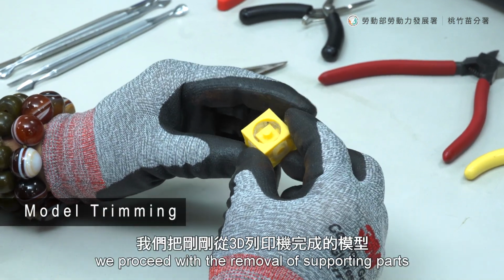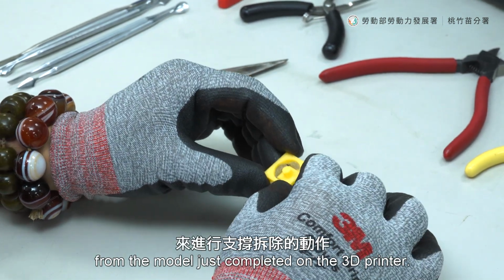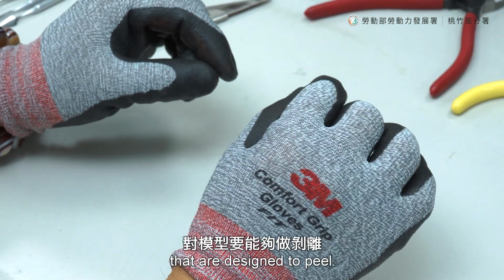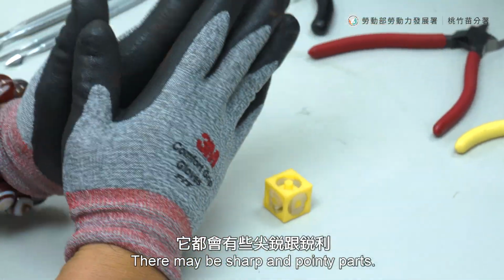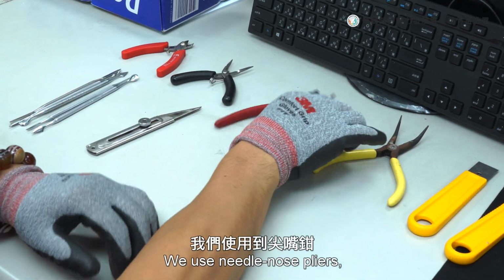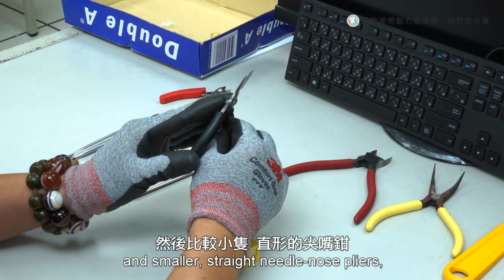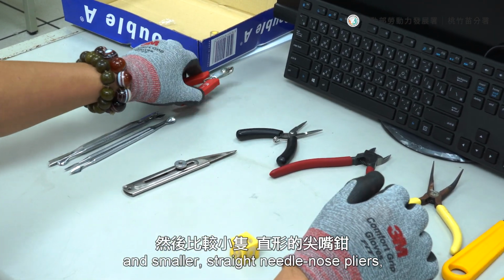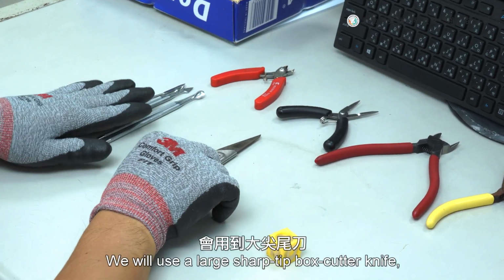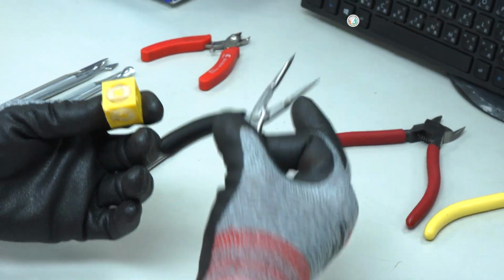Next, we proceed with removal of supporting parts from the model just completed on the 3D printer. During the process, as we are using tools that are designed to peel, there may be sharp and pointing parts, so it's essential to wear protective gloves. For safety, we use needle nose pliers, model pliers, smaller straight needle nose pliers, and finer tip model pliers. We'll use a large sharp tip cutter box and various trimming tools.